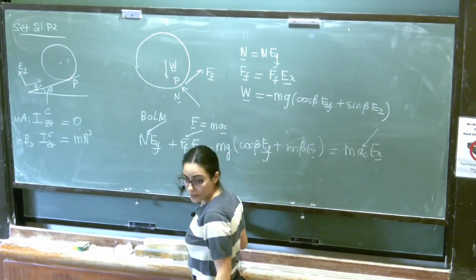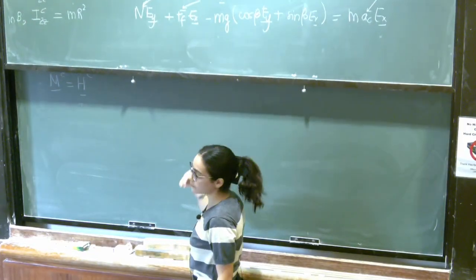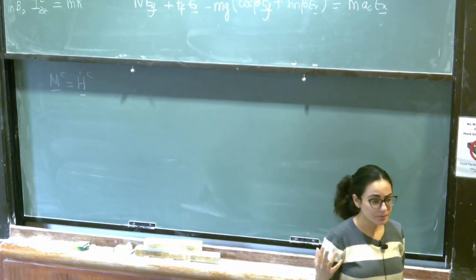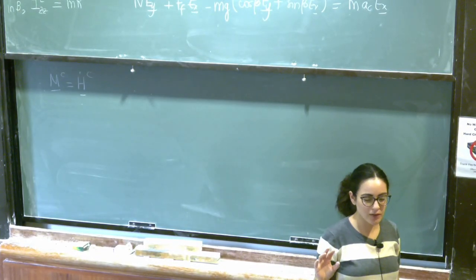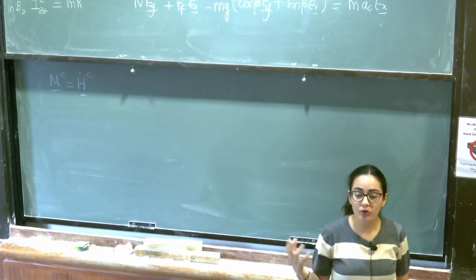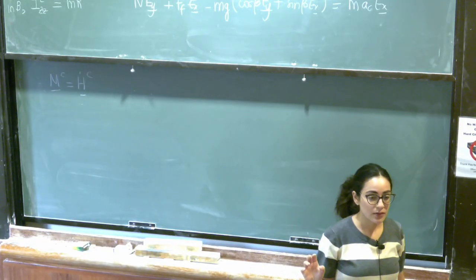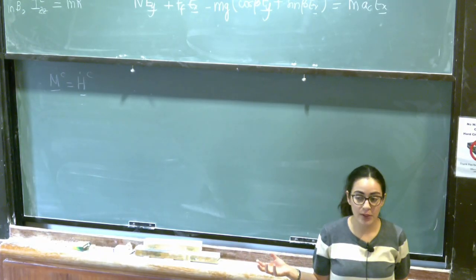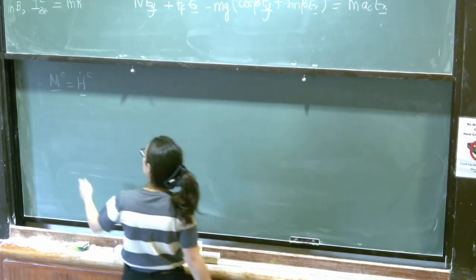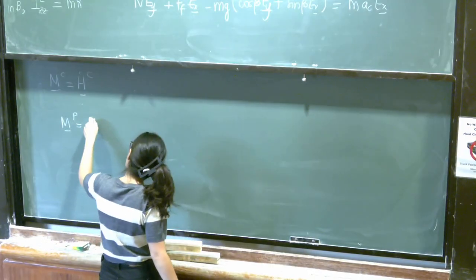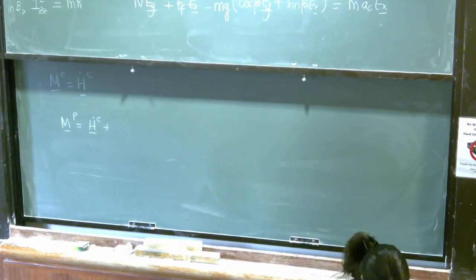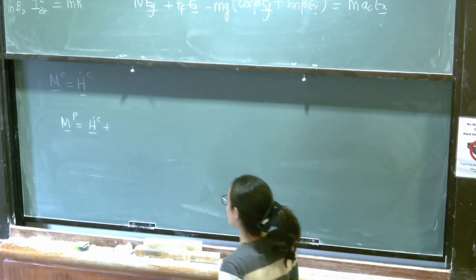Any advantage for calculating the balance of angular momentum about P? The acceleration of P is not zero, so I will not consider it to be a fixed point. But the advantage there is that what is the moment of the unknown forces, normal and friction, about P? The moment of those forces about P is what? Zero, because they're applied at P. So let us do the balance of angular momentum about P, M_P is equal to H dot_P. I have the extra terms because P doesn't have zero acceleration. It's not a material fixed point on the rigid body. (RC minus RP) cross MAC.